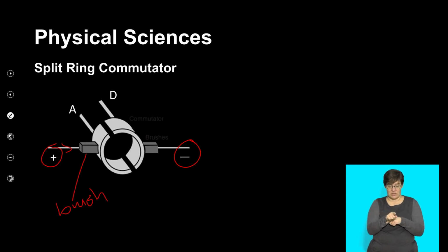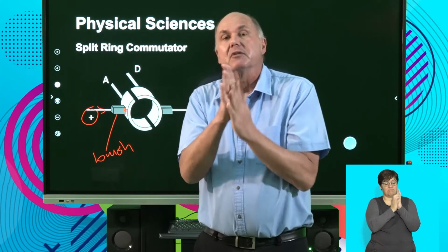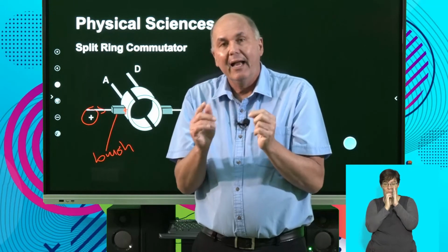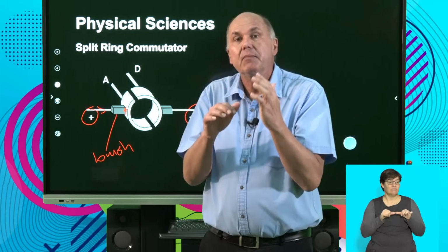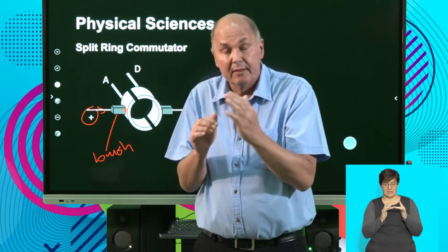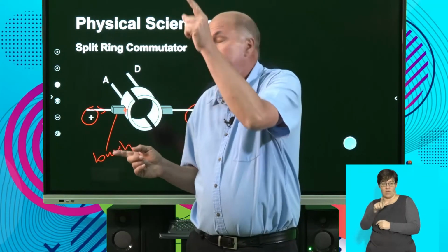The brush, there's a little gap. It's not a fixed unit. Over here, there's the cylinder that's in a coil, and that coil is free to move. It's just got contact with the bristles of the brush. And so the coil is able to move, and it's able to keep contact with the brushes. And so charge is able to flow through the wires of the brushes into the coil, into the armature.